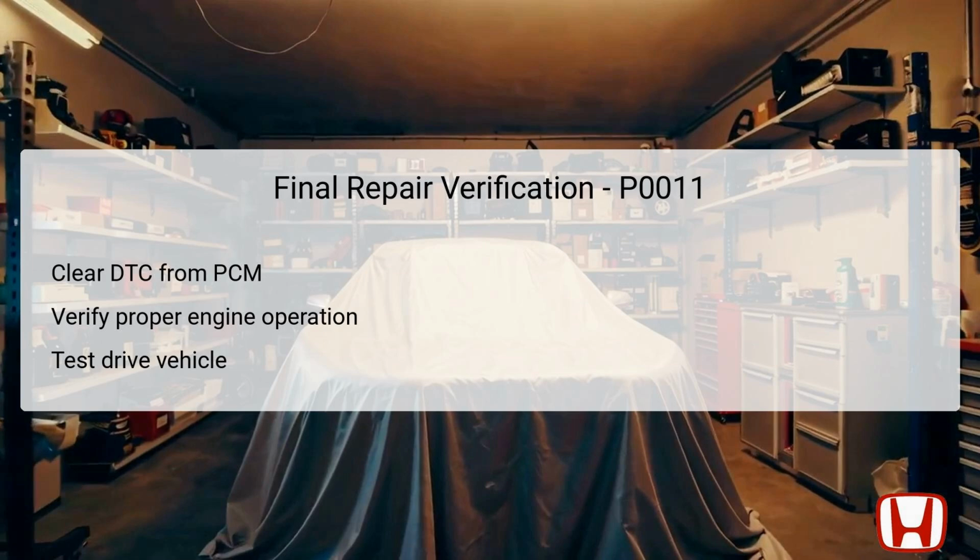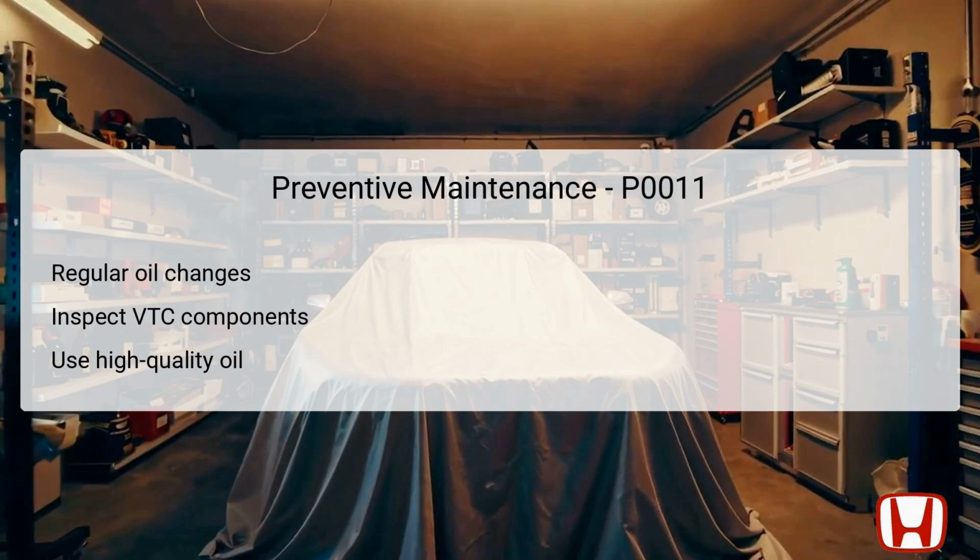A thorough test drive allows technicians to observe the vehicle under real-world driving conditions, confirming that the initial symptoms associated with DTC P0011 have been resolved. Additionally, monitoring for proper oil flow within the VTC system is essential to ensure that no lingering issues could reactivate the DTC.